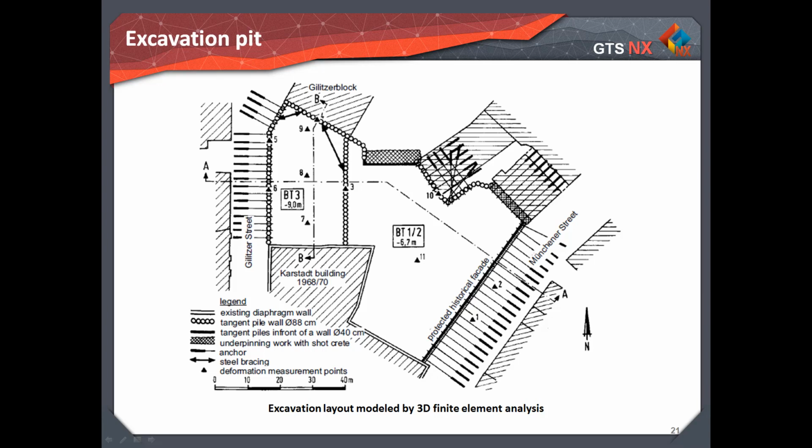Most basement excavations are three-dimensional in nature and require some degree of idealization to two-dimensional plane strain to render them tractable within a realistic turnaround time on existing computing platforms. We need to consider carefully what the effect of such idealization is on the solutions.